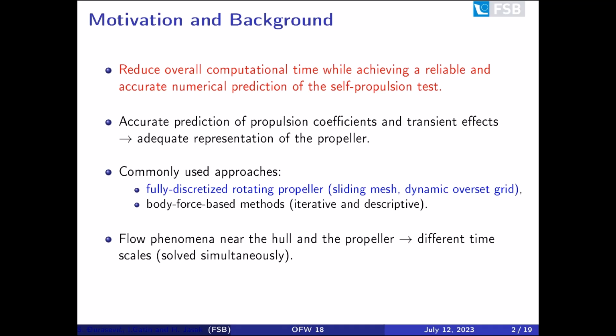New regulations regarding energy efficiency of new ships and of existing ships introduced by the International Maritime Organization increased demand for CFD in naval hydrodynamics. Application of CFD ranges from predicting self-propulsion coefficients necessary for power estimation and propeller design to a more detailed analysis of the transient phenomena induced by propeller rotation. Experimental measurements are, so to say, the gold standard, but their complexity and large costs pose limitations.